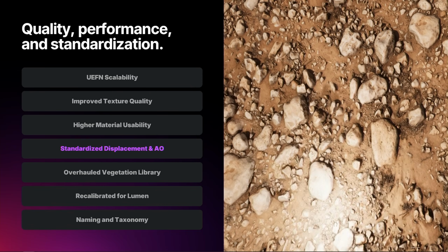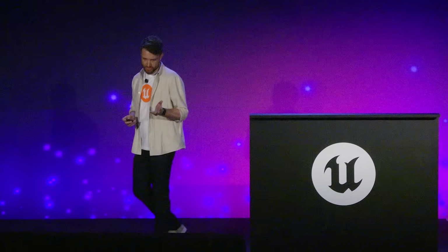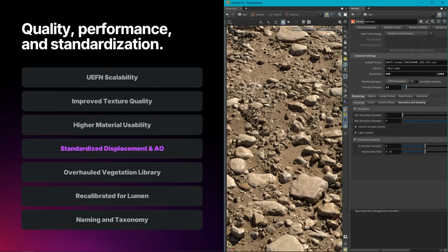One final note on this is that depending on your dicing rate that you set in Unreal, you may start to see stair-stepping artifacts when using the JPEG due to the 256 grayscale bands available in the texture. And then here's another example of the same surface, but rendered in Karma in Houdini using the EXR. In this case, the EXR was connected to the MaterialX displacement sampler with no additional values needing to be set, and this should be the case in most other DCCs.